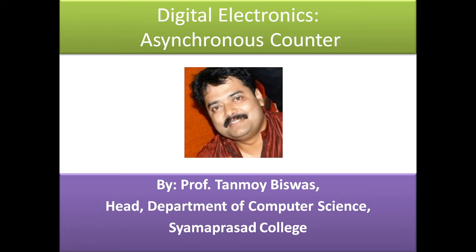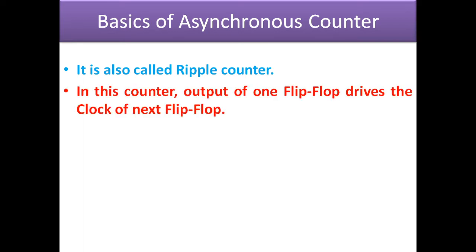In this lecture, we will take up asynchronous counter using JK flip-flop. Now, what is the basic of an asynchronous counter? It is basically known as a ripple counter. In this counter, the output of one of the flip-flops drives the clock of the next flip-flop.